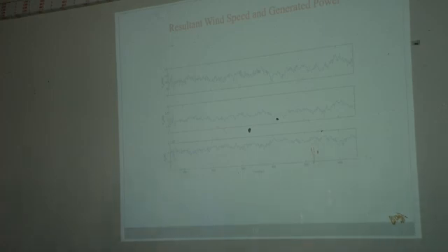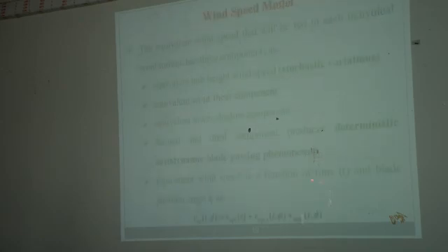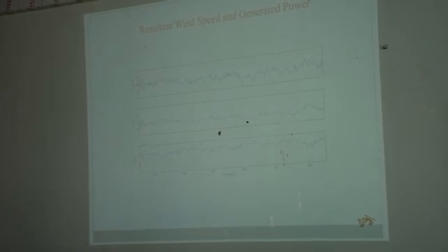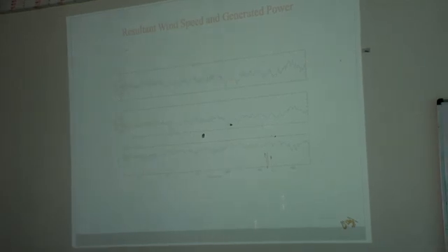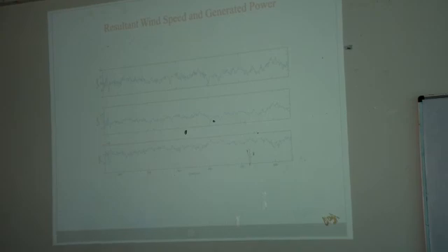Now the first thing is whether the model which is developed is okay or not. You have to verify it. So how do we verify it? We have taken an input to your wind turbine with the help of this expression, and the wind speed looks like this. Now it is not a flat profile; all the effects are coming into the picture. So these are close to the realistic effect. Then we have observed the equivalent effect in the speed of the wind turbine. That model is developed.